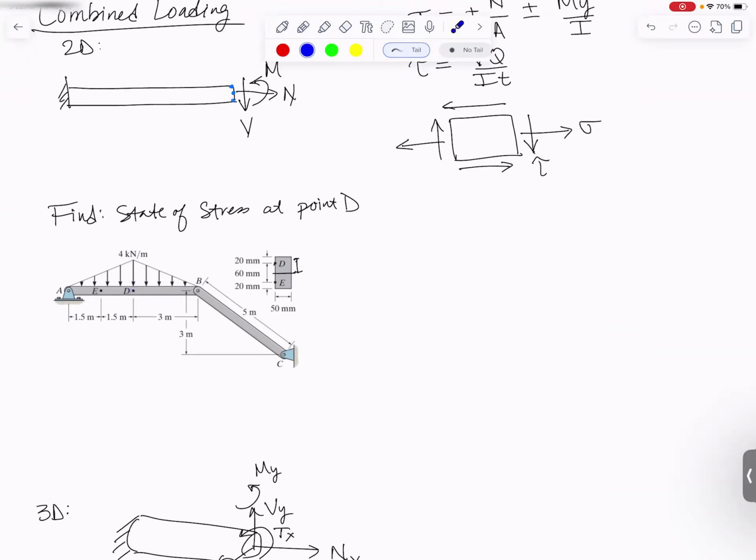So our solution process would be, number one, draw a free body diagram before you start cutting anything open to find your reaction forces. So in this case, I would probably draw a free body diagram of bar AB, because then I could find the reaction forces at A. And I've noticed that BC is a 2-force member. Free body diagram of beam or bar AB. And then we are going to use equilibrium equations to solve for Ax, Ay, and the force in BC.